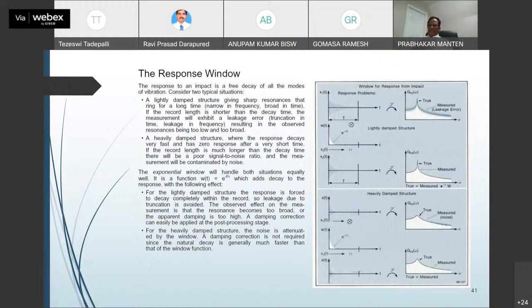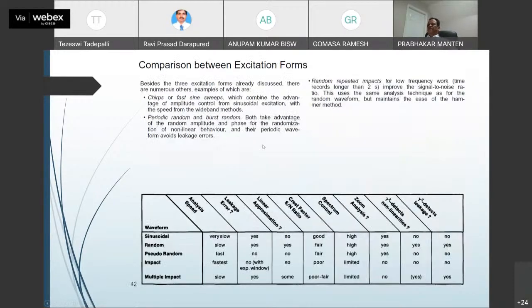If damping is crucial for your work, damping can be introduced by any and every one of these. We went through that over my lectures. But adding additional damping through instrumentation, anti-aliasing functions, and introducing windows adds another factor of damping. So if you do need to take a reasonably correct value, as opposed to what you get by applying the window, do that correction and see how that looks. The provisions are there to account for that.